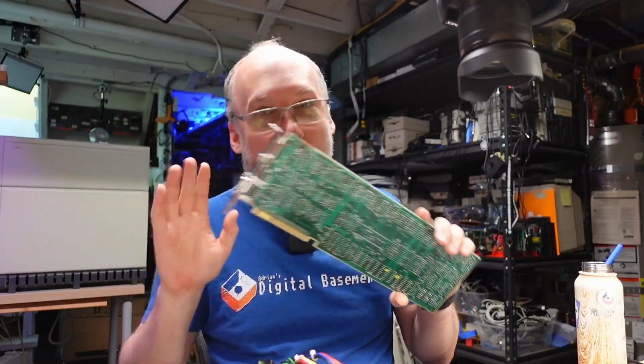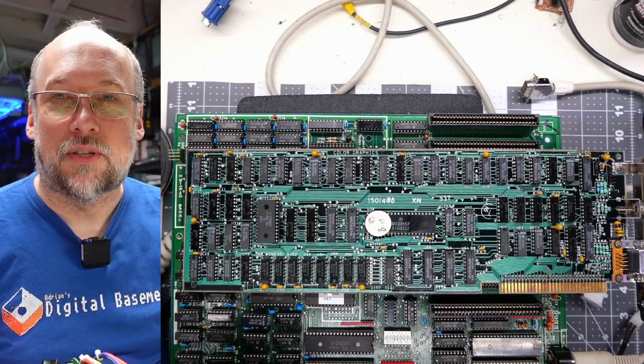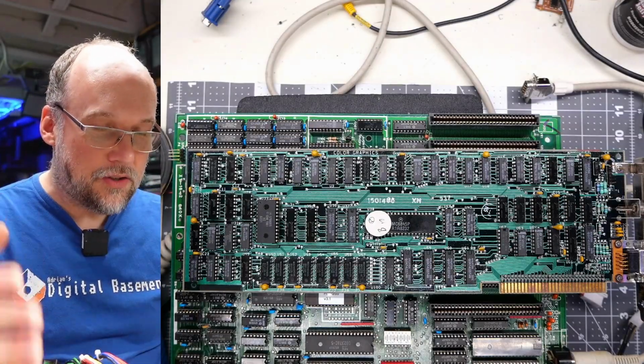So I talked about it briefly in the last video that one of the funny things about the IBM CGA card is when you scroll in DOS, there's actually a flicker. That's completely normal, and what I want to do in this video is see about modifying this card to, well, take away that flicker and maybe do some other fun stuff. So let's talk about first why it even flickers, and then we'll see about how we can mod it to take away the flicker.